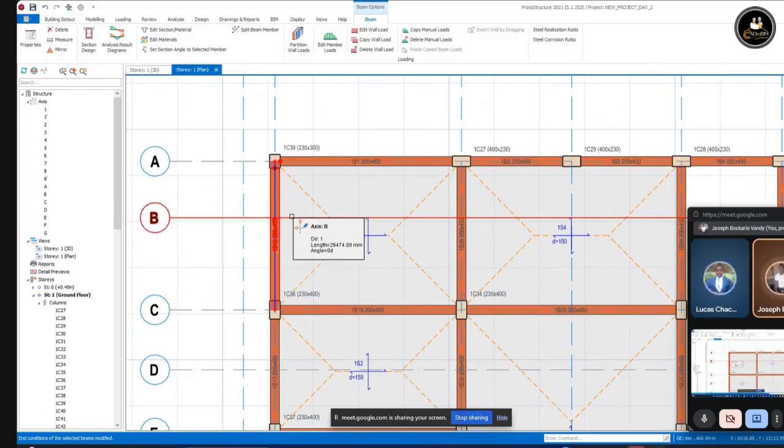And this other beam, this beam 18, we are referencing it towards this same column, but we are going upward to meet the column. We are not referencing it towards the lower side because at the lower side it is a fixed end, and by default all these connections or joints have been defined as fixed because that's the worst case scenario.